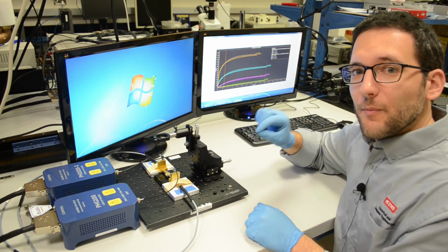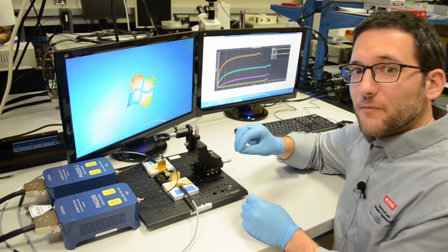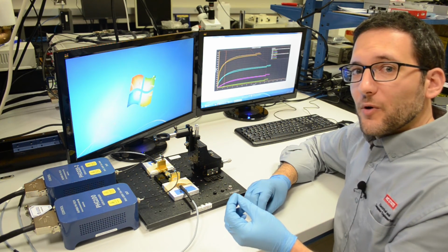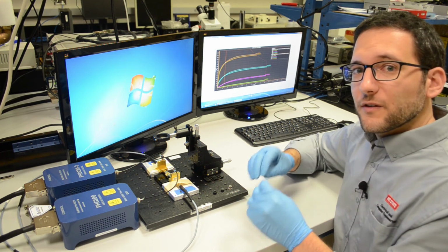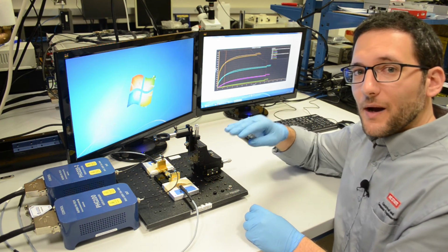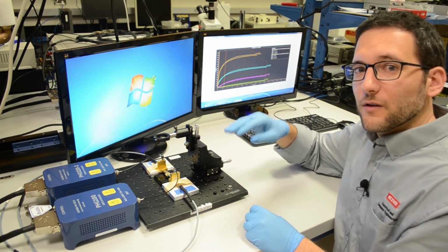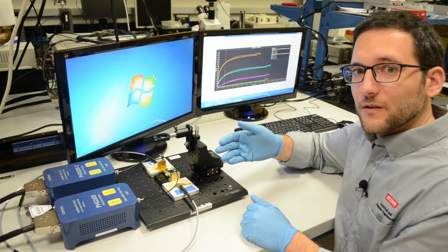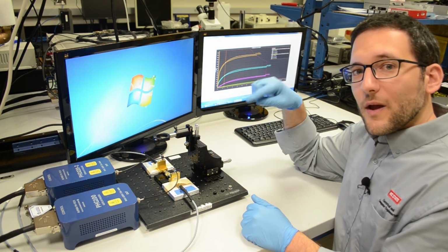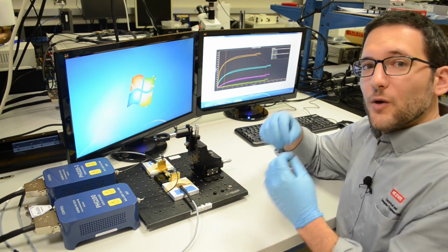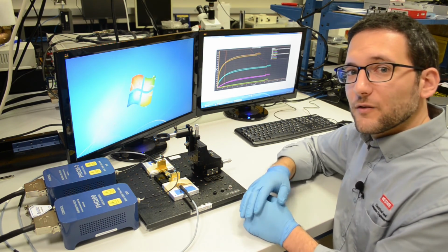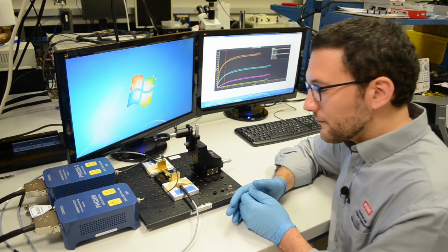This is an example of a pulsed IV system. This type of measurement is different from what we saw earlier, since the semiconductor parameter analyzer traditionally allows us to apply a constant voltage bias and measure a constant current. These are really DC measurements. In a pulsed IV measurement system, we're applying square waves of voltages known as pulses, and we can control the width or duration of those pulses down to less than a microsecond.